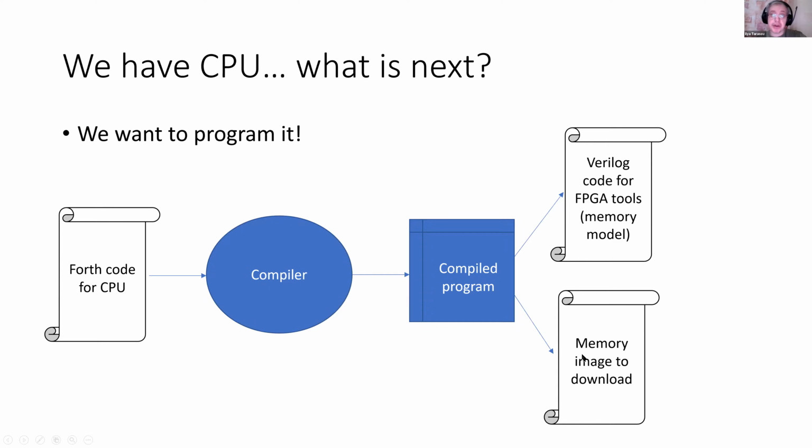It depends on the way we will use our FPGA board. For example, this may be UART. It's very common to meet USB to UART converters, and it's very easy to use with any kind of terminal program. So usually it's not a problem to implement UART.